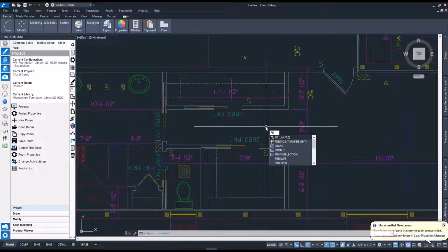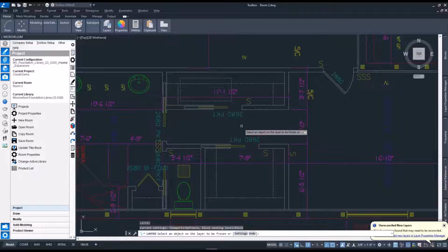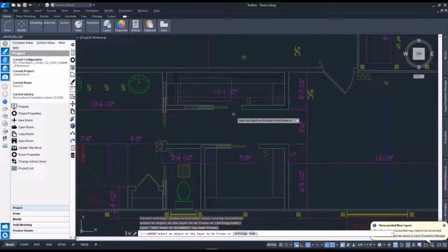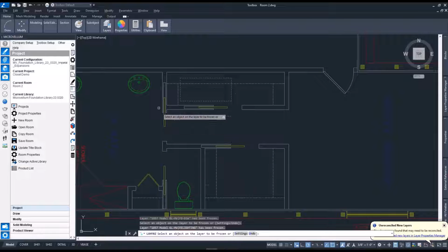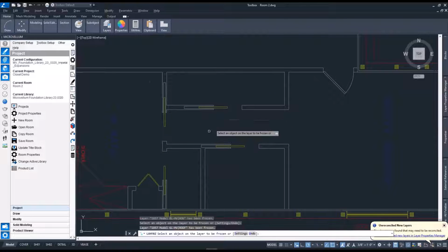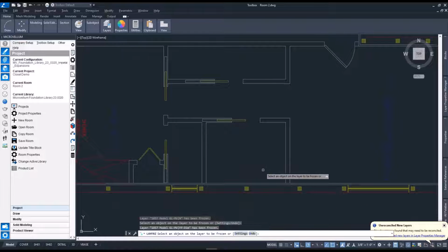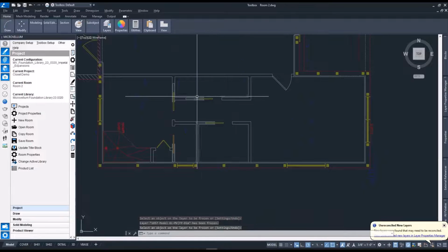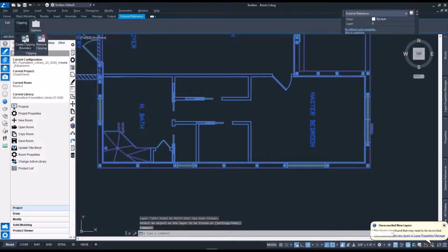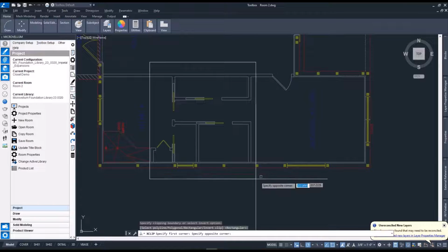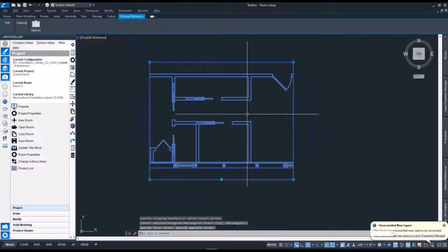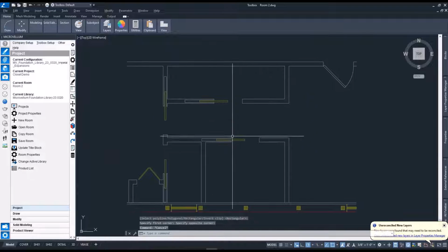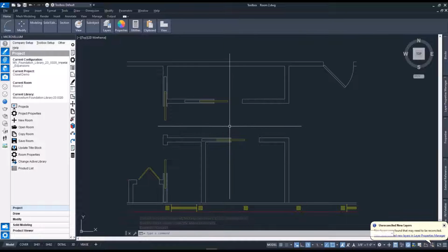Now, in this, we of course have more information than we need in our drawing submittal that we can very quickly graphically turn off through a freeze command within AutoCAD. So in this sense, we clean up our drawing the way that we want it to be seen here for our submittal. We may also have more information than we need to see around the area of our submittal. We can very quickly create a clipping boundary that just isolates the area of our design that we care about in this case. Now, from this we have a basis to work off of with very little work, but again, the level of professionalism goes way up with using AutoCAD's tools.